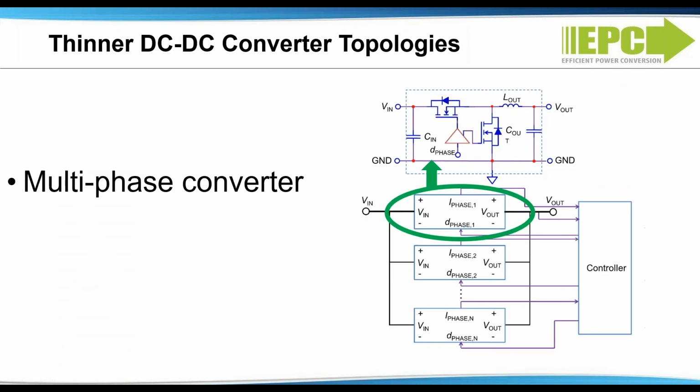The bottleneck of thinning a DC to DC step-down converter lies in the magnetic components. Designers usually have to either embed them into the circuit board or increase the switching frequency to shrink their size. The former increases design and assembly complexity, while the latter requires advanced switching techniques to maintain high efficiency. Otherwise, it'll incur lower efficiency as well as bigger thermal problems.